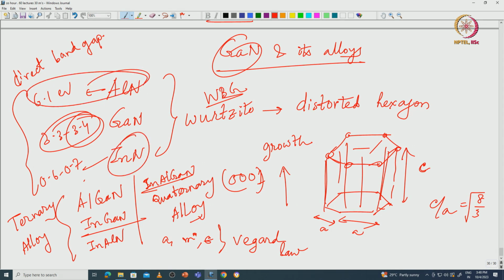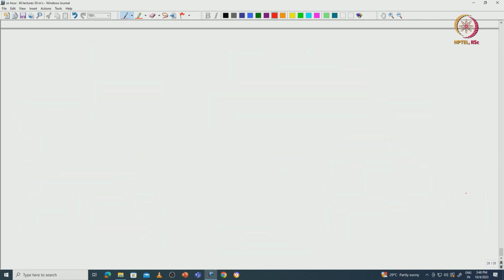Of course indium nitride is not wide band gap, but indium nitride is not so much used in RF devices. It is used in optical devices to get blue or green emission, blue LED, green LED, laser diodes, white LEDs, okay. But in RF devices typically aluminum and gallium nitride are used, sometimes indium could also be used, okay. Although I do not know of commercial devices that are yet up there which contain indium nitride in RF devices today, okay.